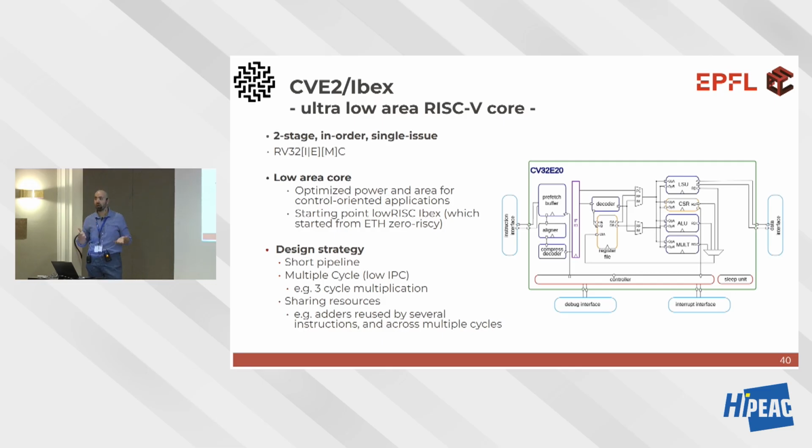And to do that, as many of you suggested today, leakage power is important, right? If you are over-designing your CPU, you are consuming power, but we are not actually leveraging this data path and these extra gates. So one of my main goals was designing the core to be small. How to make it small? Of course, you reduce all the possible extensions that you don't need.